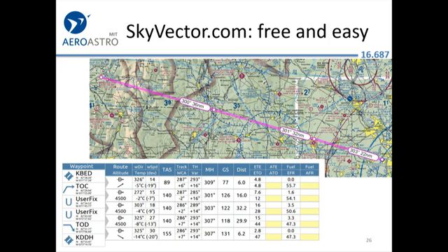So you steer that for a while, see how it goes. It's supposed to take you about 12 minutes from the time you took off to the time you reach that point, and you write down what actually happened. And if you see the airport, let's see, it's supposed to be on our left. If you see the airport on your right, you say, well, the wind's not quite what I thought. I'm going to steer 10 degrees right. And then that river crossing, I guess, isn't really ideal for heading correction. You probably want to find some other landmarks as well.